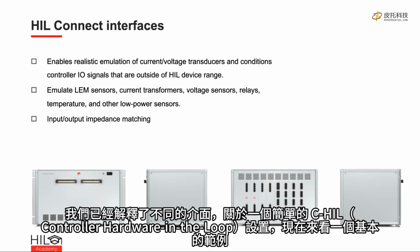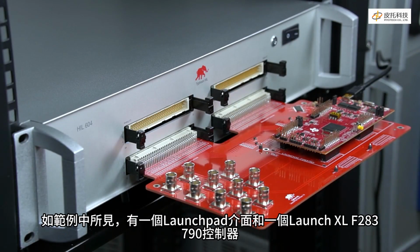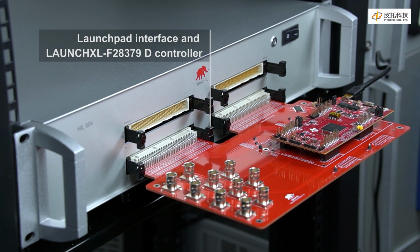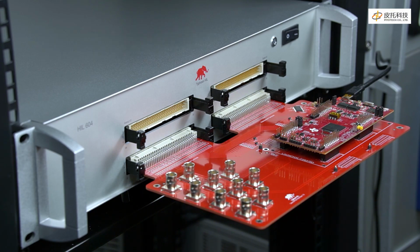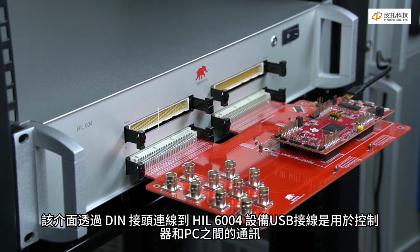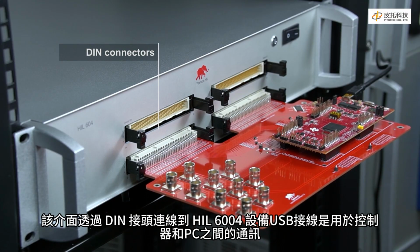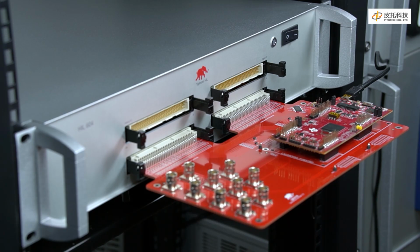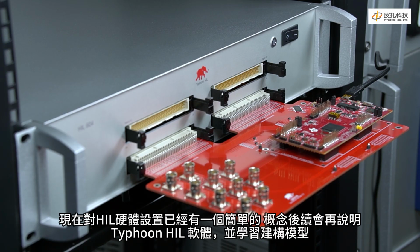Now that we've explained the different interfaces, what might a simple C-HIL setup look like? Let's look at one now. As you can see, we have a Launchpad interface and one LaunchXL F28379D controller. The interface is connected with a HIL 604 device through DIN connectors. The USB cable you see is intended to be used for communication between the controller and your PC. So now you have an idea of what a simple HIL hardware setup looks like.